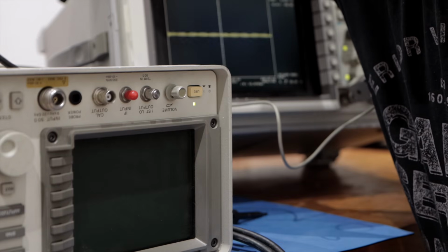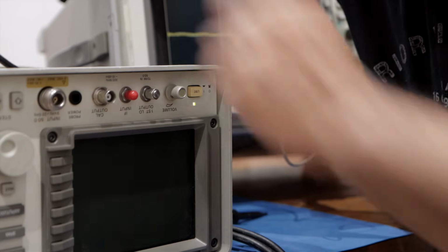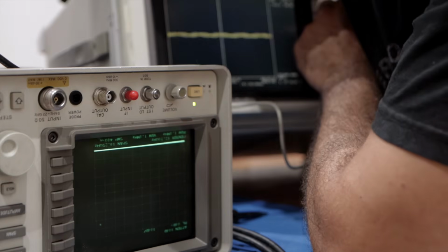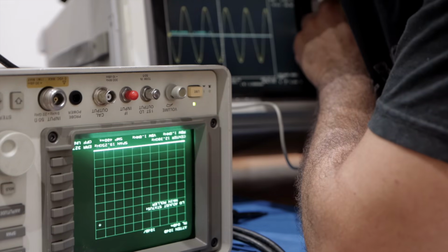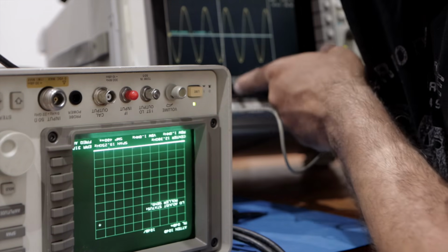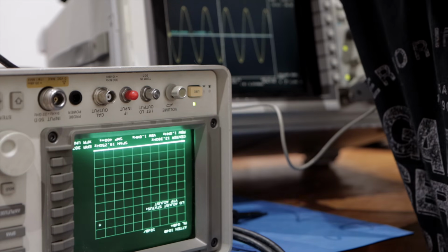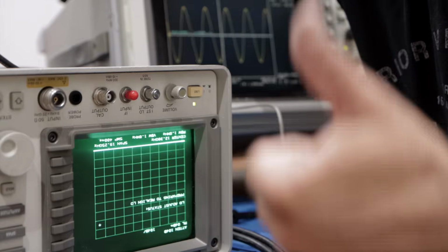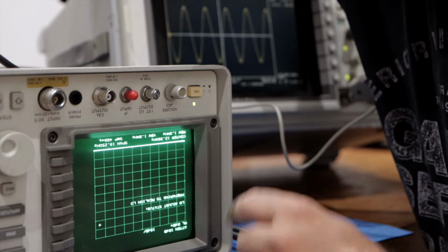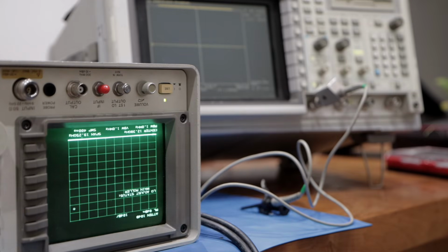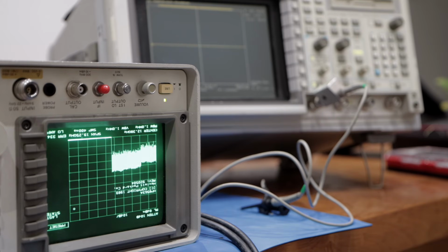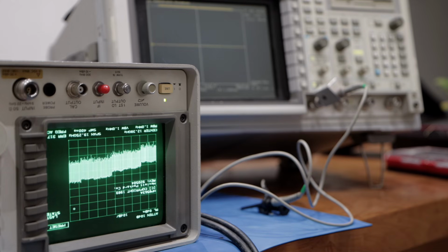Moment of truth. Before testing the analyzer, I'll quickly check the signal with my oscilloscope. Look at that. You can barely see it, but I'm getting a super clean 10 MHz sinusoidal waveform. Way better than what I got from the frequency counter. Let's plug it back into the analyzer and fire it up. A few errors are still popping out, but yes, there it is. The noise floor is back. One problem down.